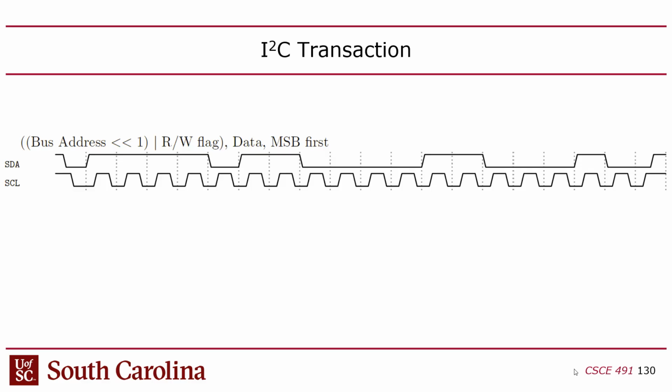And then we're writing, so control is passed back to the master for a write, right? So if we look at the data bits, it's the master now that's driving the data, even though you wouldn't know from the timing diagram. You would only know from interpreting the protocol. So what is the master writing? 0011, that's a 3.